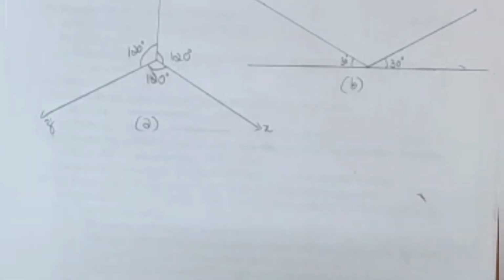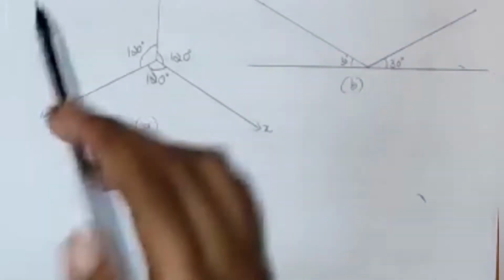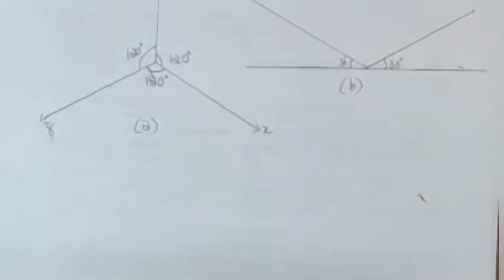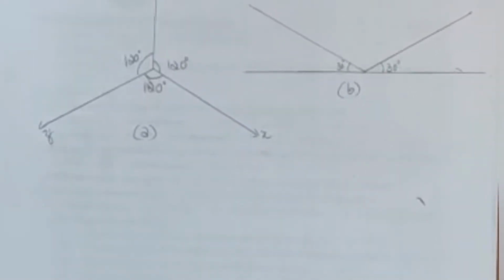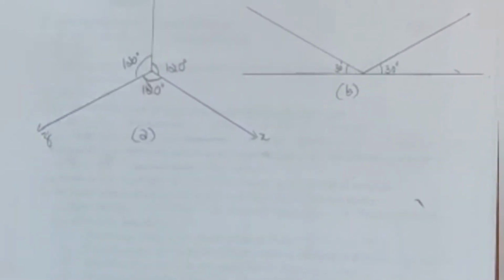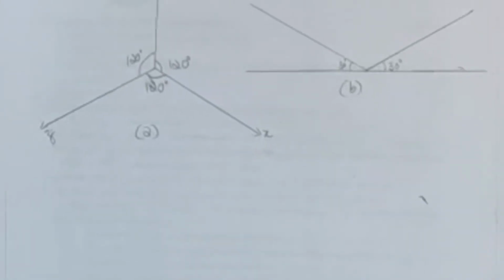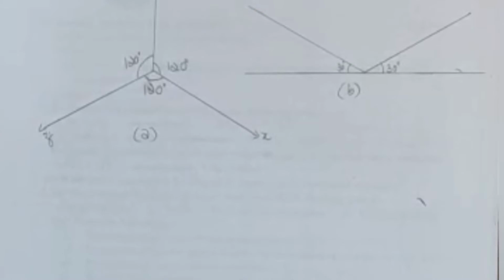Now I'll be taking up the isometric views and projections part for engineering visualization course. Isometric projections, this is a method for visually representing 3D objects into 2Ds in engineering drawings. The word isometric is derived from the Greek language meaning equal measures. Isometric views are a simple way of representing a three-dimensional object so that the complexities of a shape can be clearly understood. It is a type of graphical projection in which all three dimensions of an object are shown in one view. Orthographic view shows only two dimensions in any particular view.